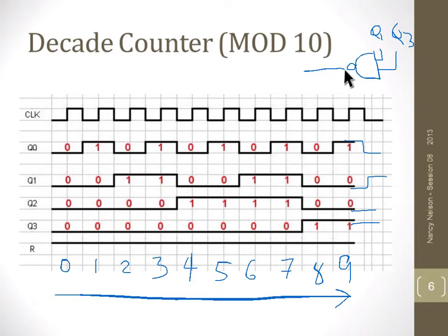What happens? This immediately resets. Every flip-flop goes to 0. And what we're going to see is very quickly, this drops back to 0, this is 0, this one is high, it drops back to 0, and by the time we get to that next rising edge on our clock right here, we're going to be sampling and we're going to see a 0 output.